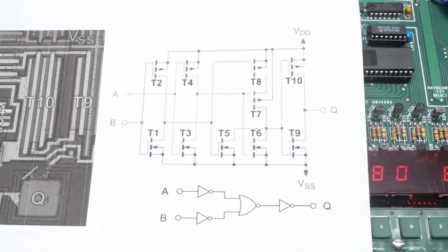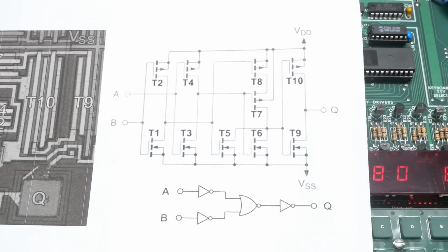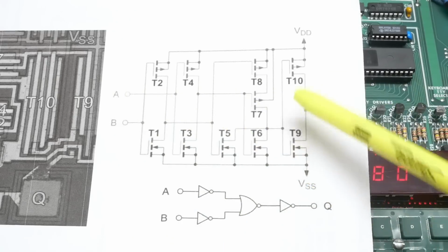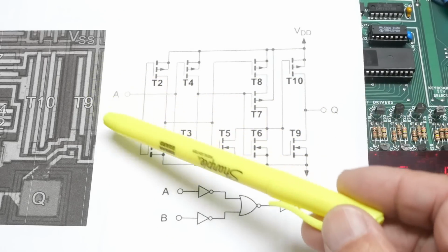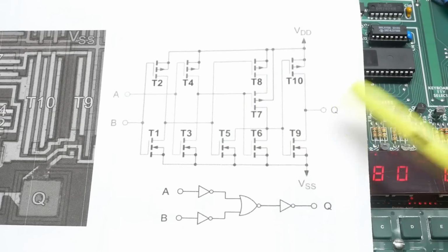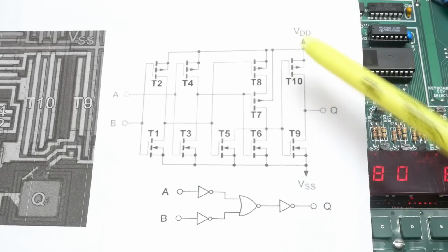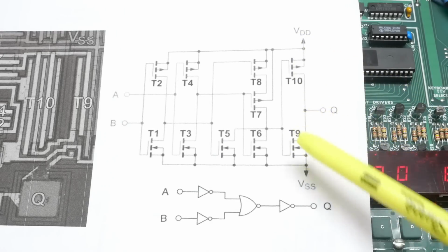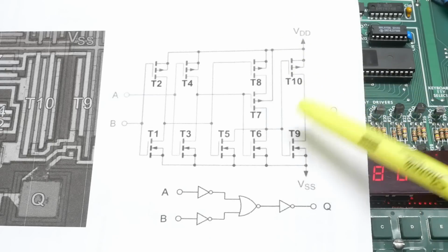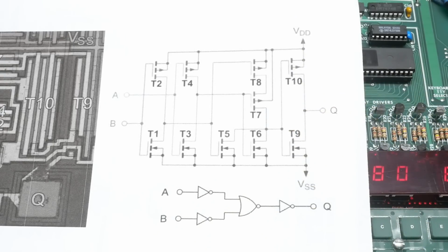All right. Here's what you might be used to in modern day. This is a CMOS chip. And it's actually a pretty old CMOS chip, but it's CMOS. And if you take a look at how it's constructed, this is A and B, and then this is the output Q. And you can see that there's a transistor on the output that can pull it high, and a transistor on the output that can pull it low. And so it can pull it high really good, and it can pull it really low really good. All right? But what about the old days?